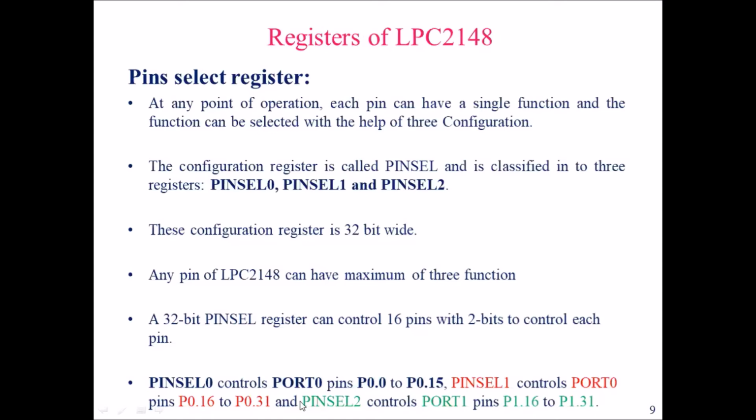And the third pin select register, pin select 2, will control the port 1 pins. Whereas pin select 0 and pin select 1 both control port 0 pins, pin select 2, the third register, usually controls the port 1 pins, from P1.16 to P1.31.